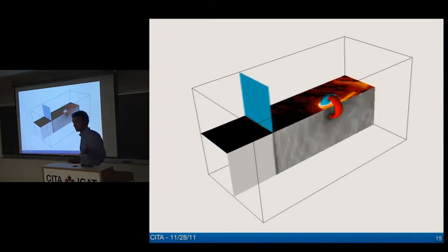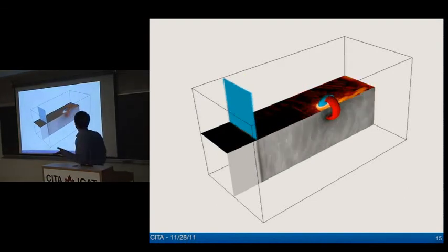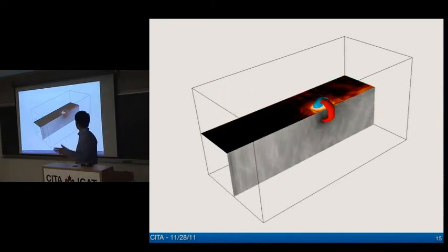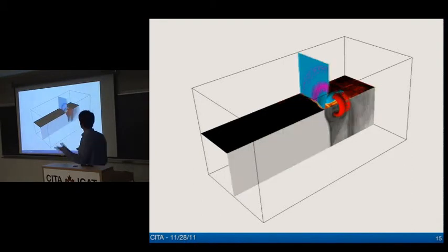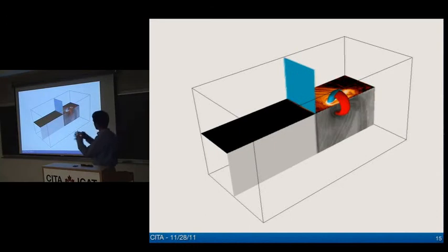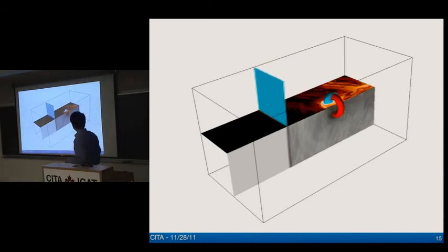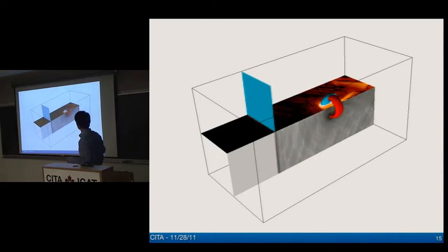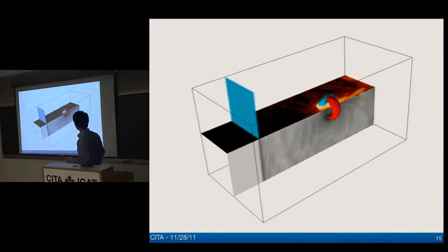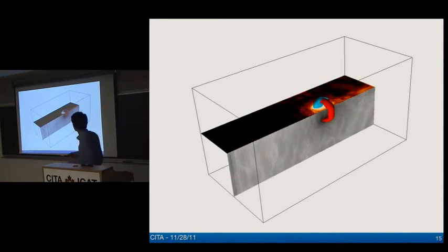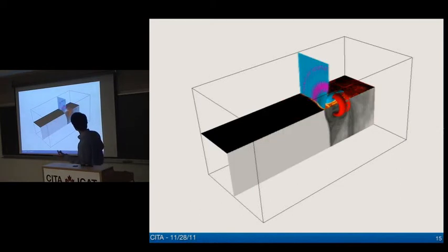Okay. And so this is a well-known process, and it's essentially a macroscopic representation of what's known as the Richtmyer-Meshkov instability. This is an instability that occurs when you have pressure and density gradients misaligned. That's why this term, the cross product of pressure and density gradient, is important. Whenever this term is non-zero, you create vorticity. And so you can see where the vorticity is generated, and you can also see it in the shock wave over here.